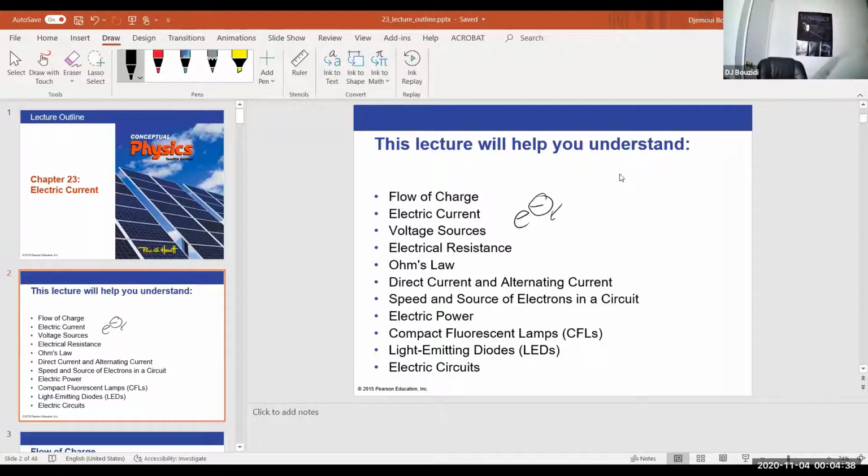Let me grab another one, because this one is connected already. This is a resistor. You can see the camera is trying to focus on me, so hopefully it's going to focus on it instead. Okay, so this is a resistor, and you can see it's color-coded. If you have a magnifying glass, you can see exactly what the colors are and read the value based on the color. Otherwise, connect it to a multimeter and it's going to give you the value. That's another quick and dirty way of getting the values.